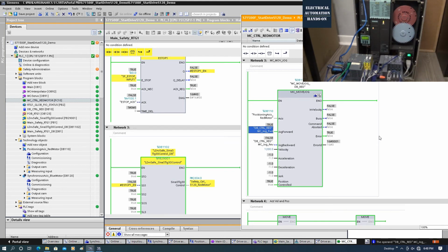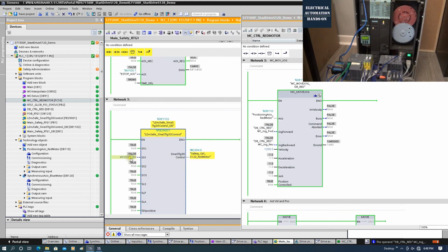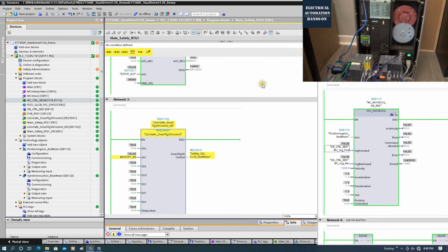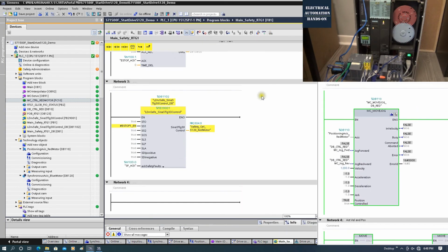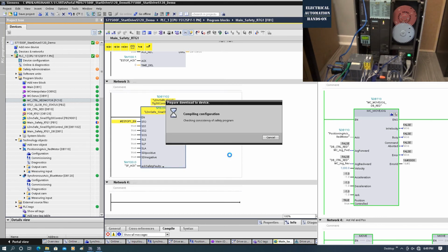And next step, we will try STO, safety torque off. It's just a run down, lose the torque, and stop by itself. And I will give this enable move to the STO. Let's see the difference between the STO and the SS1. Okay, I will move this enable to here. Okay, and we need to download the controller, compile and download.